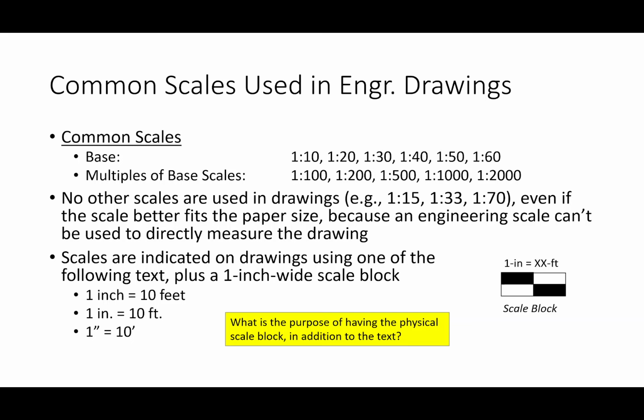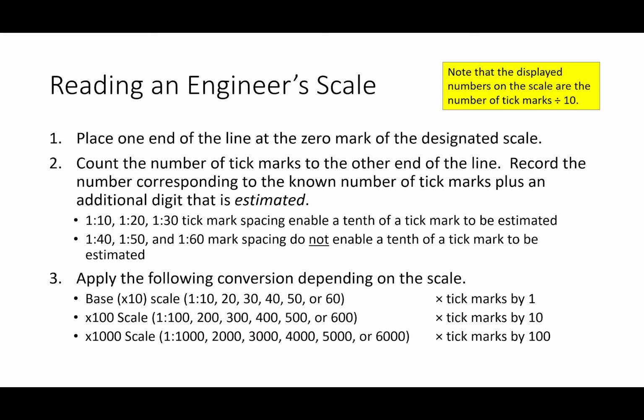Well, a good reason is to check the scale of the drawing. For example, if I turn to my 40 scale, let's see, where's my 40 scale, right here, and I place my 40 scale on this block, you'll see that it's exactly 40 feet. So it's a way of verifying that the scale of the drawing is indeed correct. Okay? Does that make sense? Don't worry, I'm going to hand these out in a little bit.